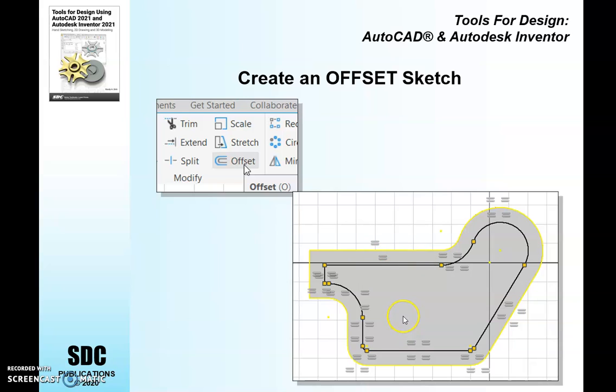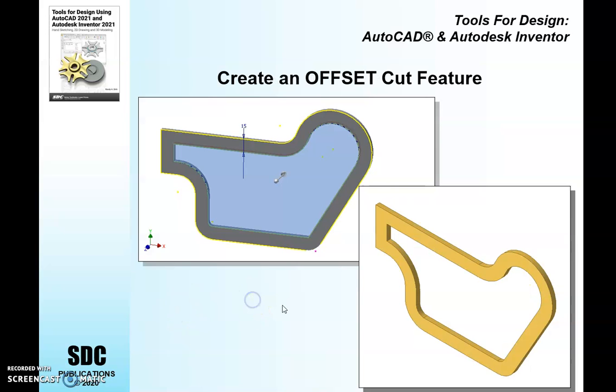Basically, he's going to project the old sketch onto the surface of the front and then offset that, so that by offsetting it, it keeps all of its geometric constraints, like parallel, perpendicular, and conserves angles usually during a projection and an offset. The offset command you'll end up using a lot. So this is our first little case. We did offset a fair amount in AutoCAD. This one works similar, but not exactly the same. And then he'll go in and cut that out. And then I think he has you do one more dimension change after you've done it.